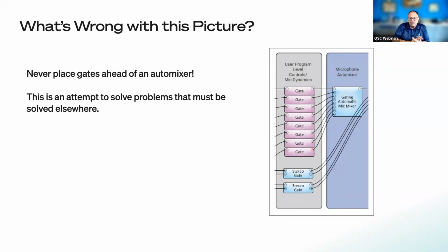It's a bad thing. Here's the rule of thumb. Don't put gates before your gating mic mixer. And don't put user volume controls before the gating mic mixer either. That's another no-no.